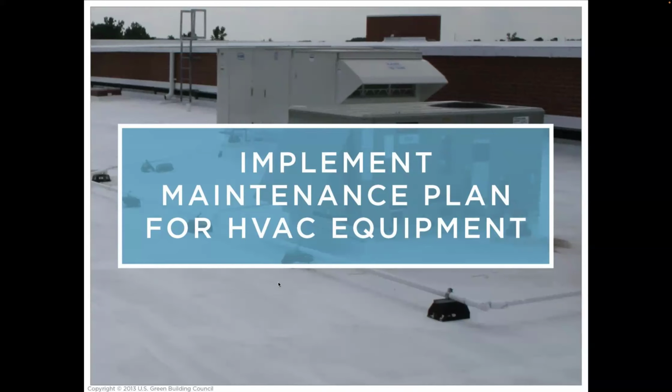Your filters, for the first place, can get super old and clogged, and so the more dust that they've trapped, the harder it is to get the air through there. So again, you're wasting energy there. You may have some motor issues. You may have other issues, your outdoor air economizer may be broken. And you can only catch that when you go and maintain it.